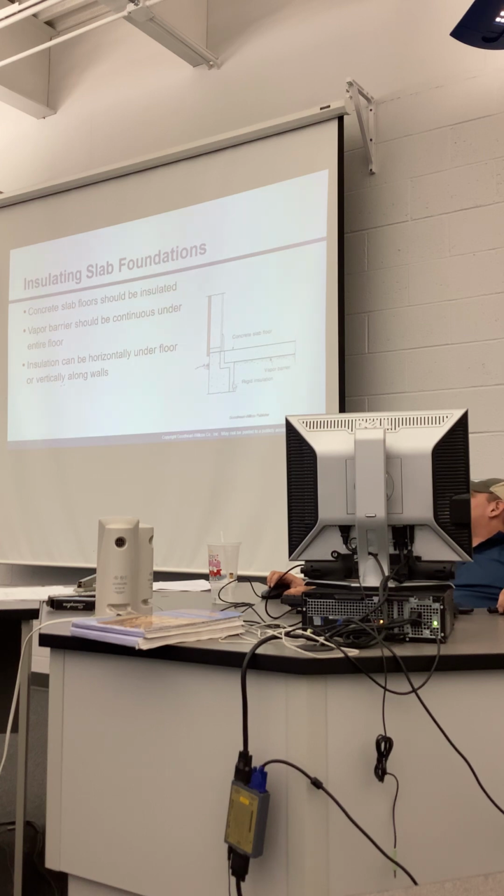You guys see this? This is insulation that runs up and runs out in between this floor slab and here. Why wouldn't I say that's a good way? You have water issues, you have bug issues, you have mice issues. If they get underneath into your crawl space, they can come up, they'll eat through this insulation and come up. That's why I don't like it.